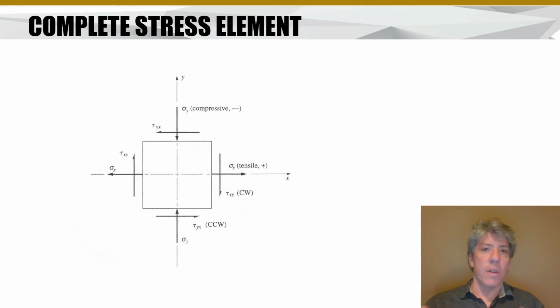And then any combination of load is really something that can be broken down, think of vector decomposition, into a normal and a shear stress. So it's possible we could, in reality, say on the x face on the right hand side, we could think of adding the shear stress and the normal stress and ending up with a vector that's sort of down and to the right. Wouldn't necessarily be at a 45-degree angle. We could go anywhere from horizontal, where there's no shear, all the way down to no normal stress with just pure shear, right?